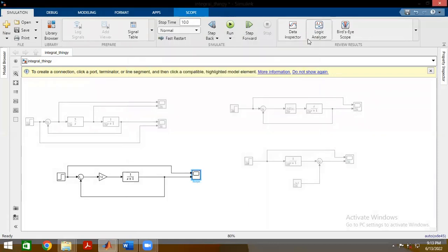So why would we go for something that gives us steady state error? Why would we make our system less accurate? Why would we do that? By the way, this is called a proportional controller because all we're doing is multiplying, amplifying the error with a constant. So be it that constant is 0.1, 2, 12, 100, doesn't matter. This is called a proportional controller because you're multiplying the error by a constant, right? Hence proportional controller. All right.